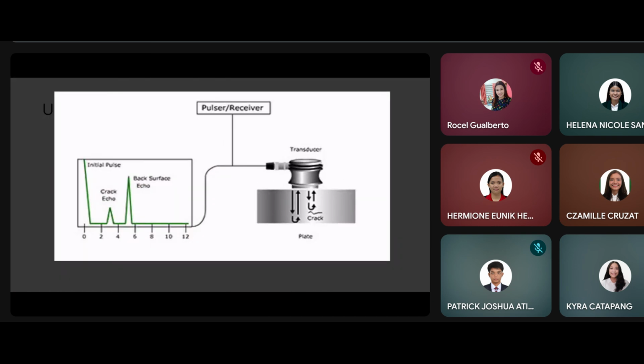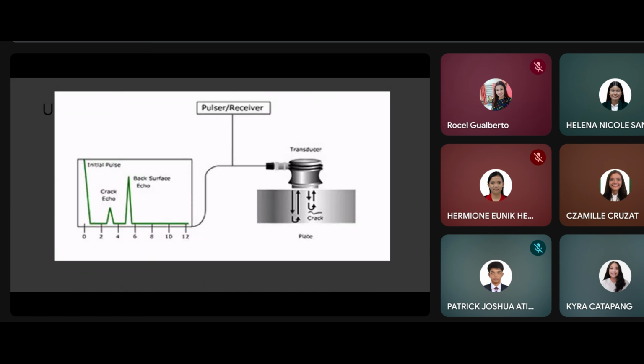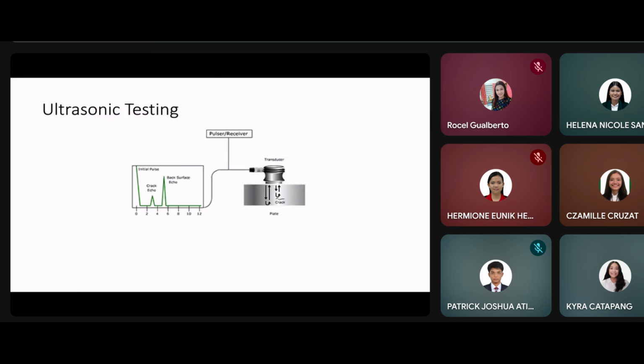Ultrasonic testing is yet another technique in NDT which uses a piezoelectric transducer connected to a flaw detector, which in its most basic form is a pulser-receiver and oscilloscope display. The transducer is passed over the object being inspected, which is typically coupled to the test object by a gel or oil, or sometimes we could use water as well. The signal received from the transducer can be analyzed with the help of a computer interface.